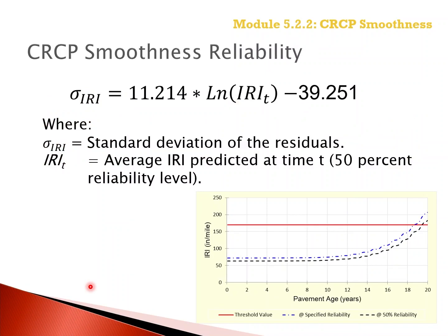Reliability was discussed in detail in Module 3 and how it is applied in the PMED design software. The standard deviation of the residuals for IRI are displayed on this slide. The standard deviation of residuals is used to determine the reliability of the IRI that is predicted for CRCP.